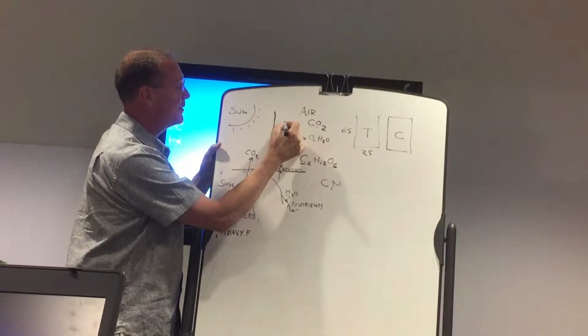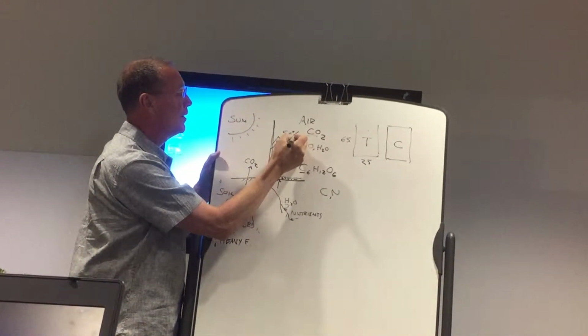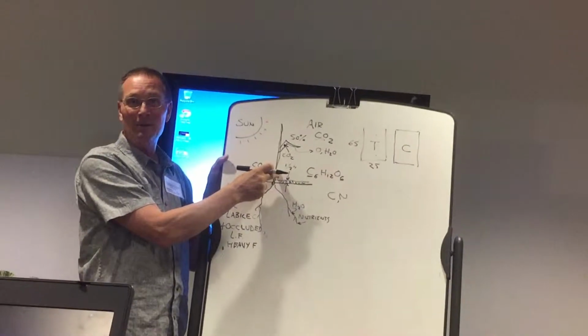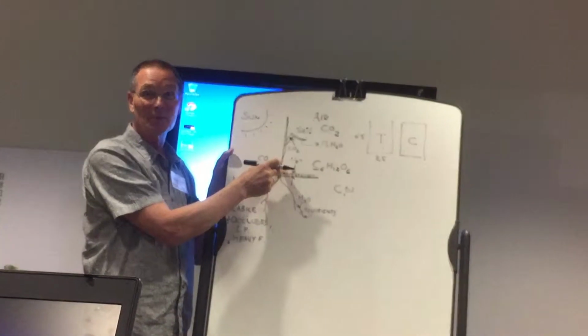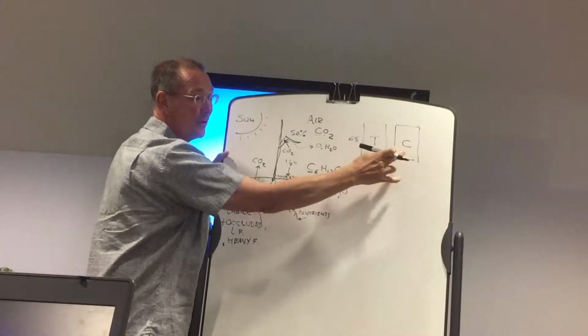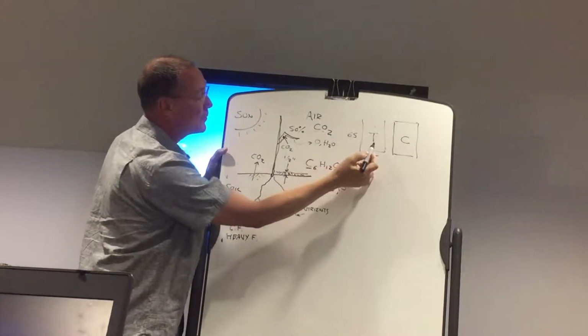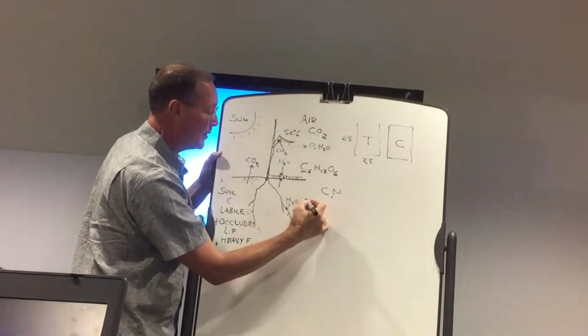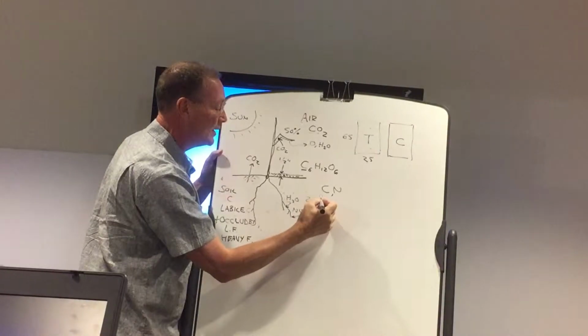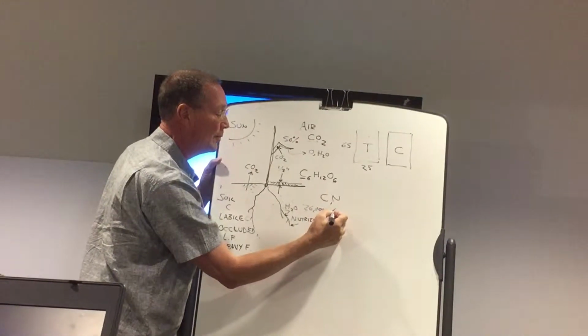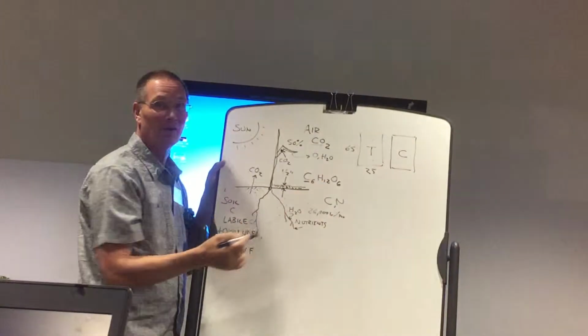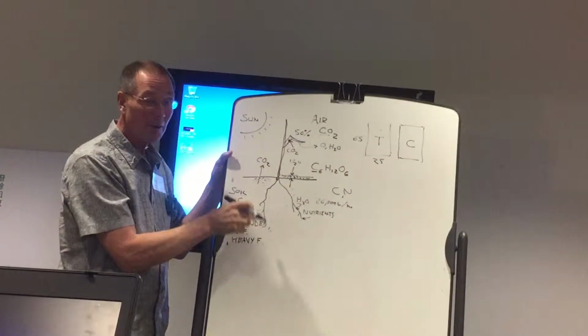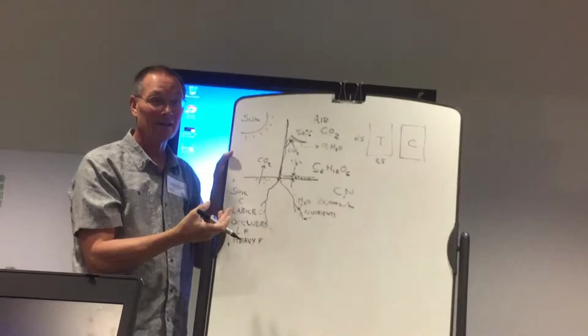Immediately for the vegetation, we saw 50% more grass, and it was higher nutrition. So it's better grass compared to the control. Because of the soil moisture probes in the water, we measured 26,000 liters more water per hectare compared to the control. So that water holding capacity was measured. It was significant and important.